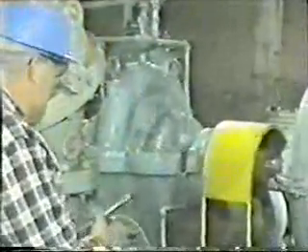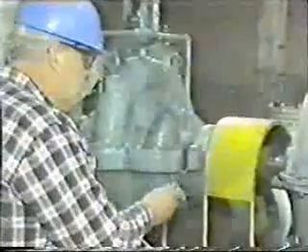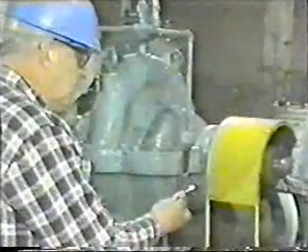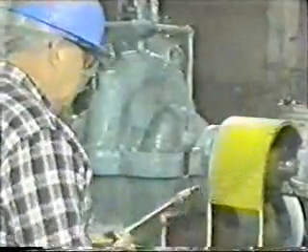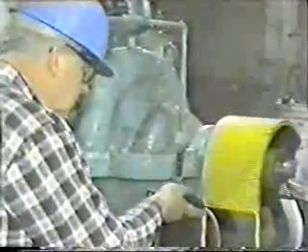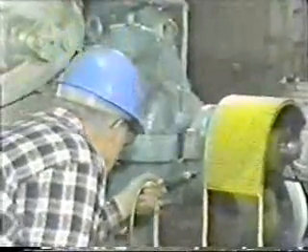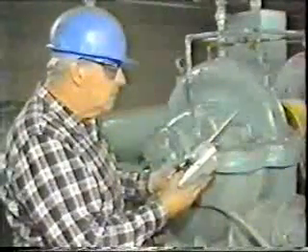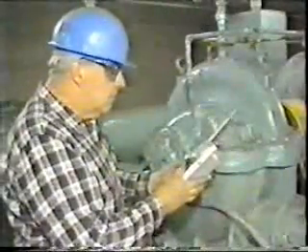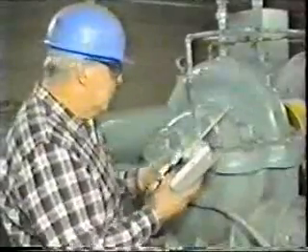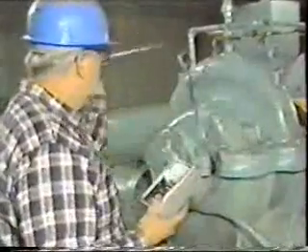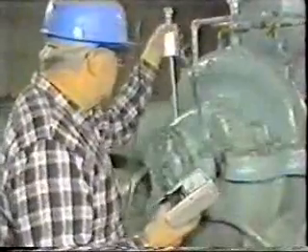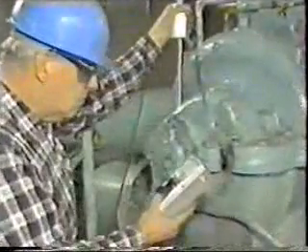Gene goes on to check the temperature reading on the other pump bearing and on the two motor bearings. You'll remember that the operator told him there was no temperature increase on the other bearings, but it's good practice to check both bearings. After finding the temperature at the other pump and motor bearings to be normal, Gene makes a check for excessive vibrations at the outboard bearing. Excessive vibrations could indicate bearing failure.